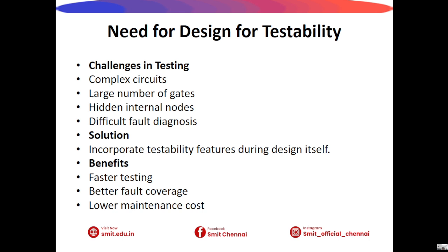Next, we see about the need for design for testability. Modern VLSI circuits may contain millions or even billions of transistors. Accessing internal nodes directly is often impossible. Without DFT, generating test patterns and identifying faults becomes extremely difficult. DFT helps overcome these challenges by providing better access to internal circuit states.